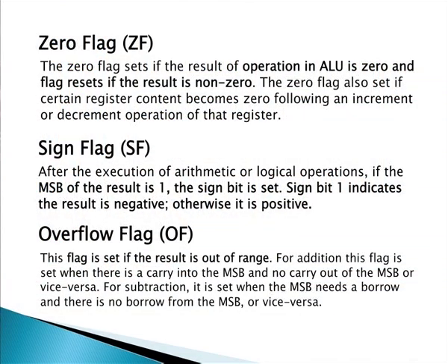Now, the question arises: what is the difference between a carry flag and an overflow flag? So, let us be clear. Carry flag, we say that when a carry is generated from the most significant bit position, then carry flag is set to 1. It is simply saying that a carry from MSB is part of the result, but the overflow suggests that your result has exceeded the maximum capacity, that is, the storage capacity where the result will be stored. Overflow never suggests that it is part of the result, it is just suggesting that your result has exceeded the maximum storage capacity.